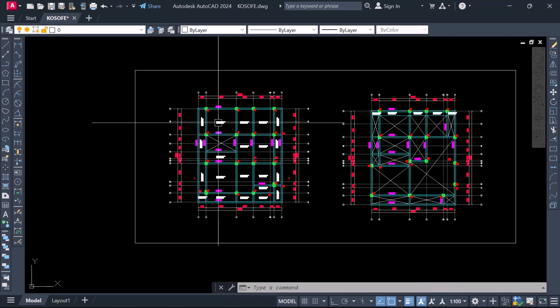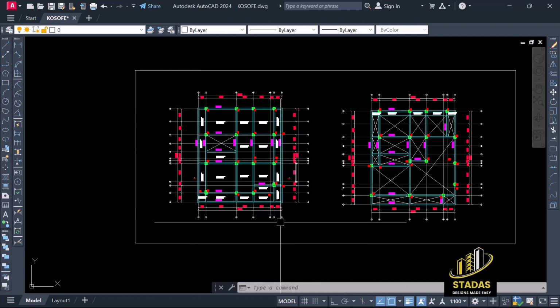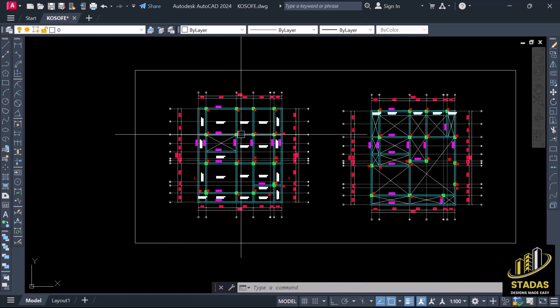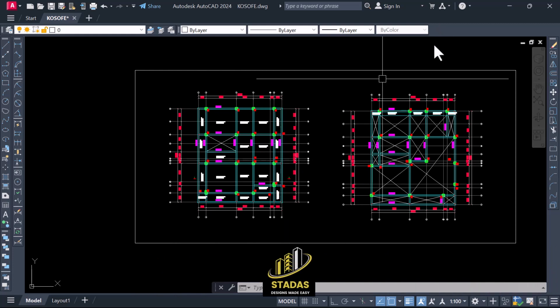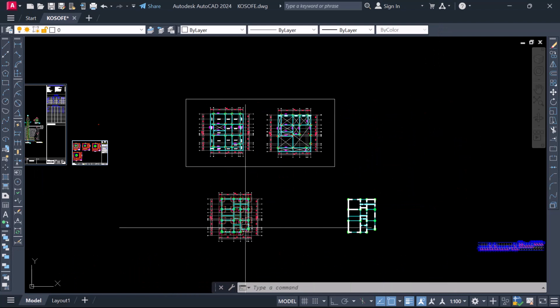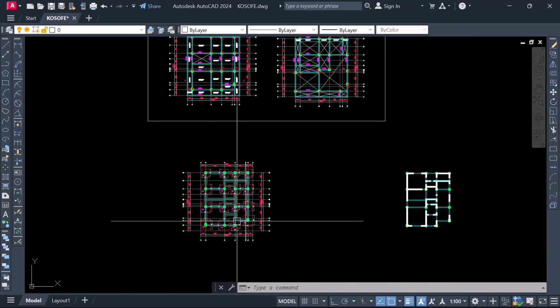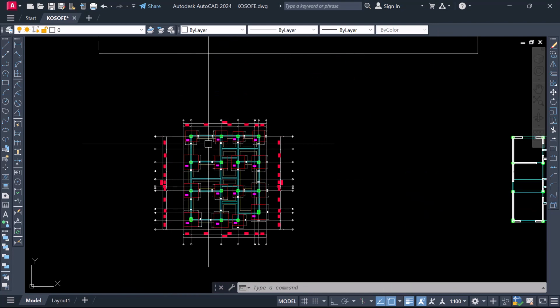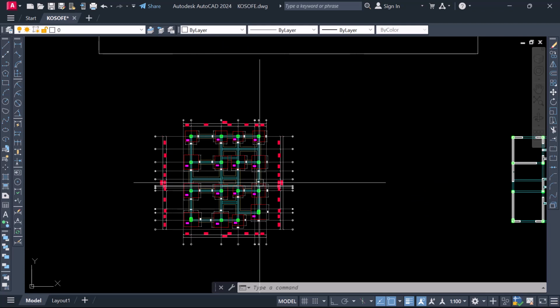So we're taking off all the dimensions of the cantilever areas, because this cantilever is not going to be projected down to the foundation, right? So we projected the foundation. What we did is just fix the area which we needed, that is where the column is going to sit on the ground. This is the pad footing, and on a pad footing you're expected to send only the columns down.